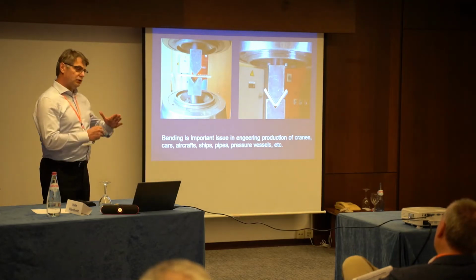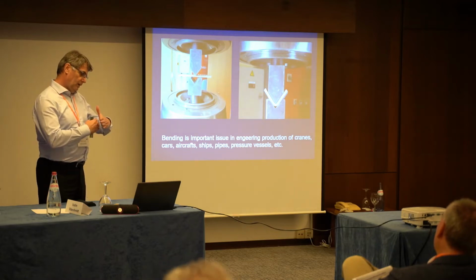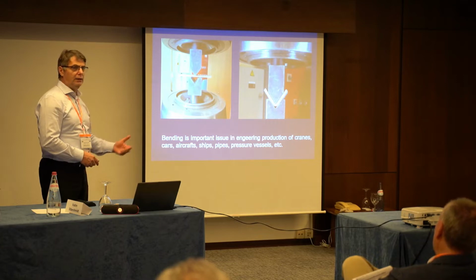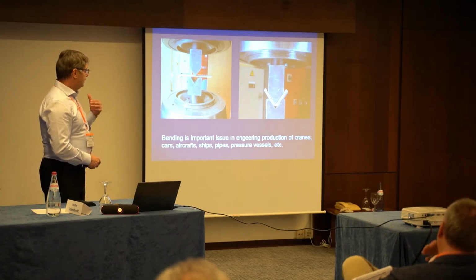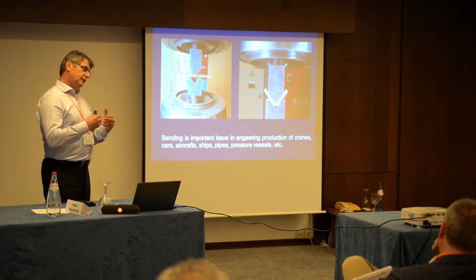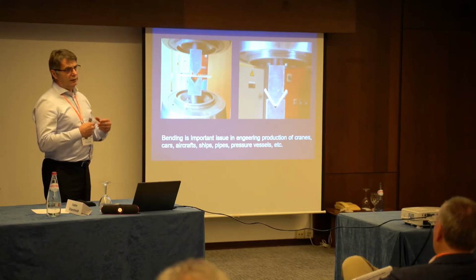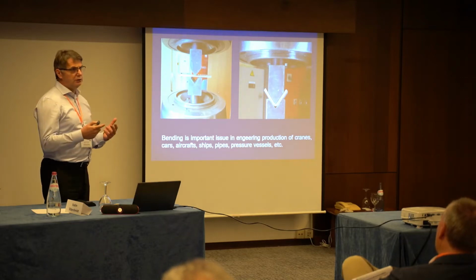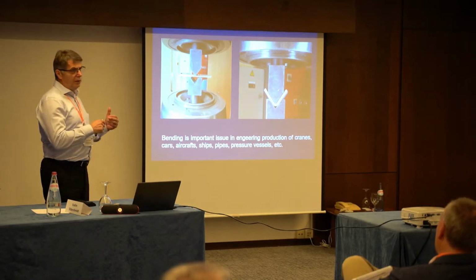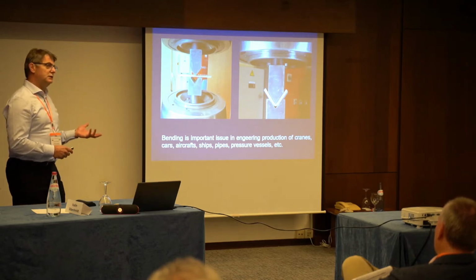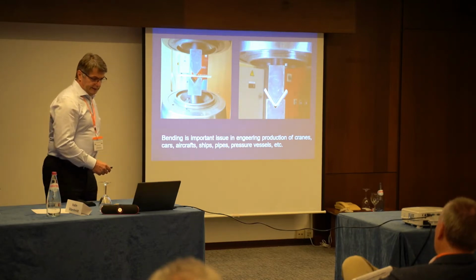But of course, because you're doing the bending, you always have a neutral part which remains austenitic. During the fatigue loading, with fatigue crack growth, at the crack tip the material changes properties from austenitic to martensitic, and so this is the interesting issue for analysis.